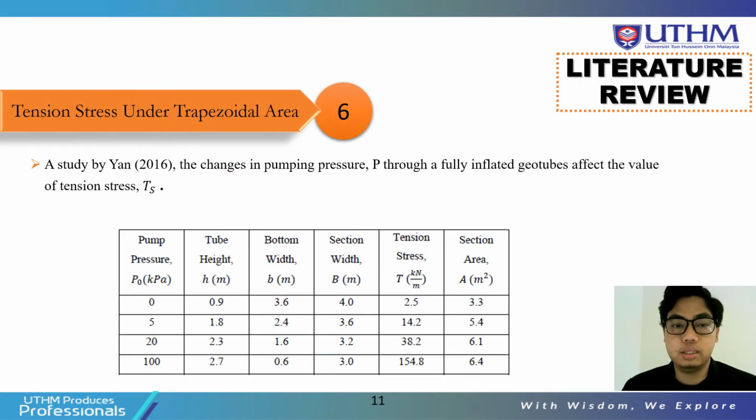Next, for tension stress under trapezoidal area, a study by Yan in 2016 studied how the change in pumping pressure through a fully inflated geotube affects the value of tension stress. Below is the table for the result of the study by Yan.